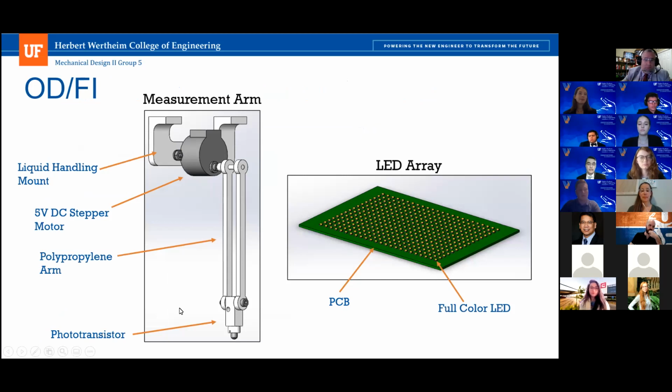No, so that was designed to be a rigid connection, so it would be a tight fit. Now, the reason it is not a solid beam is in the event that the sensor itself breaks for whatever reason, it's easily replaceable. So you could simply undo the screw and remove that sensing system, or if a wire comes undone. It was essentially made for ease of manufacturing because these are 3D printed parts.